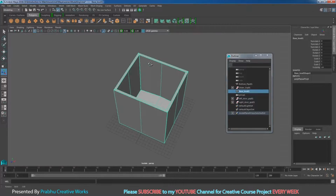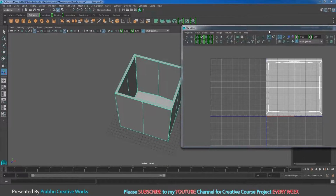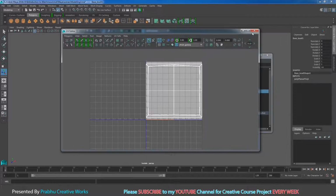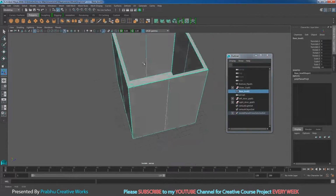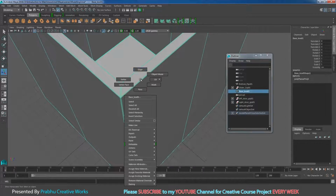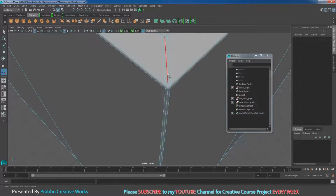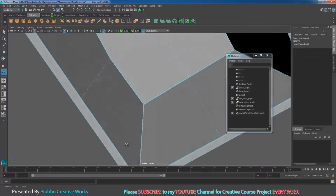Now I want to go to UV and choose UV Editor. See here, we got our projection over top. Now I close my UV Editor. Now I want to select the corner edge. Right click and choose edge, then double click on the middle corner edge over here, which means the entire loop will be selected from top to bottom.